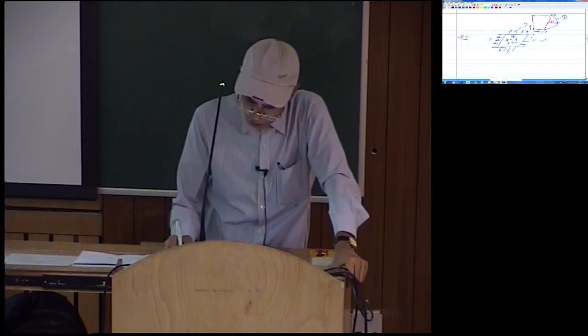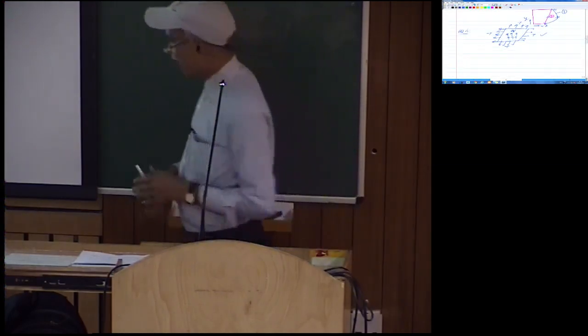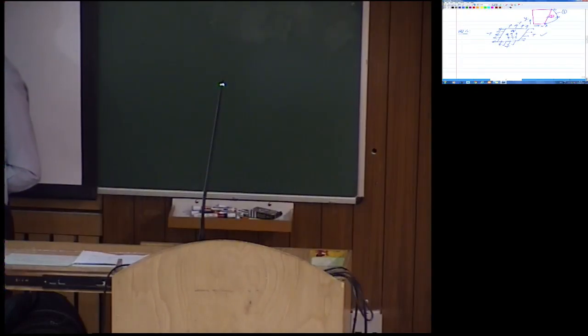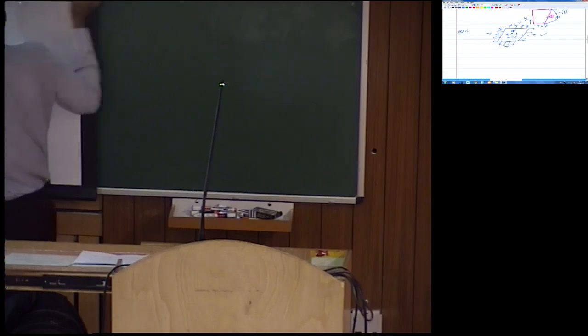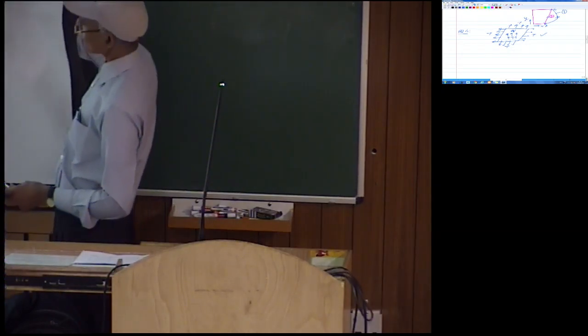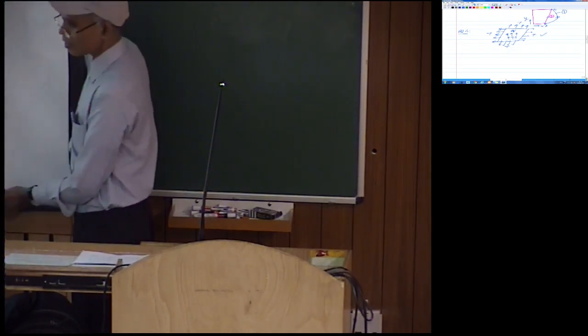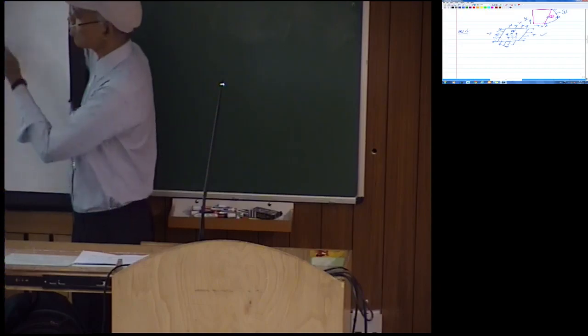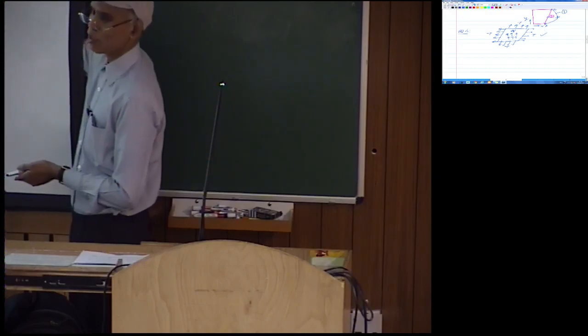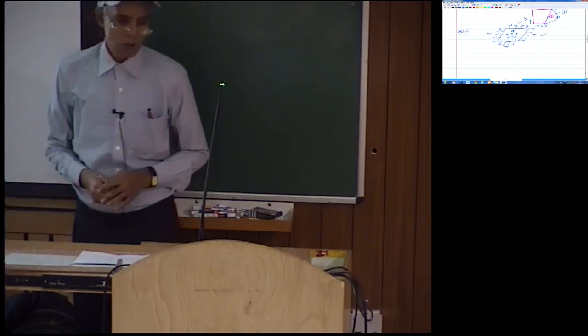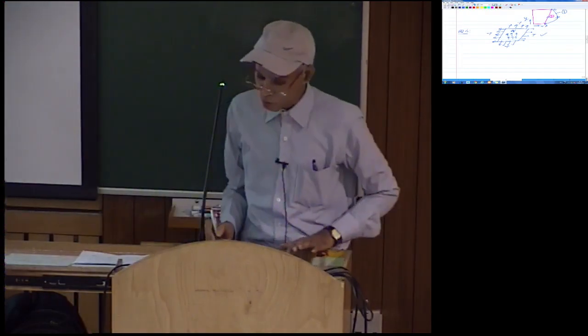So this was, of course, straightforward. Physically the problem is like this: because of the weight of this rod, it has some in-plane tension, although in this case there is no tension in the other direction, so we have to differentiate Tx and Ty, and then if you apply a transverse load, you want to solve the problem. So this direction, I think it touches the wall, so you are applying a load like this, it has already an in-plane tension and a transverse load, you want to study how it is going to deflect, and of course you can also look at the stresses. So that was the problem, the question number 4.